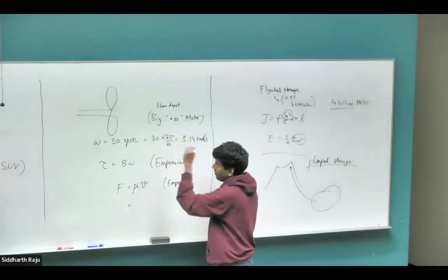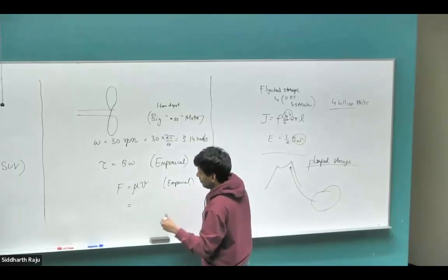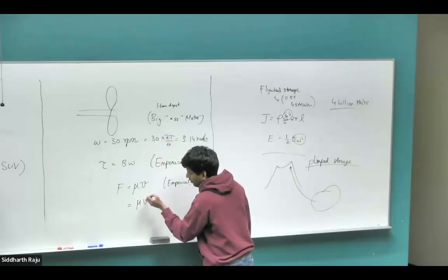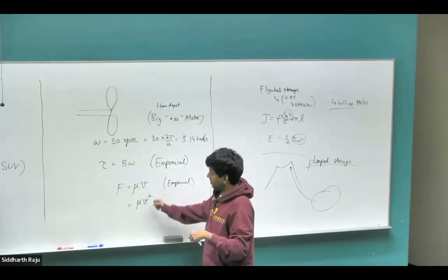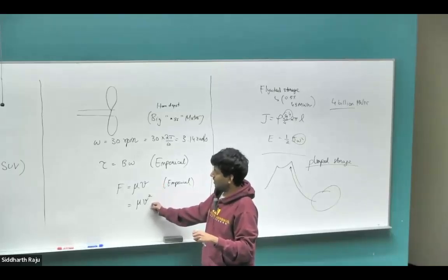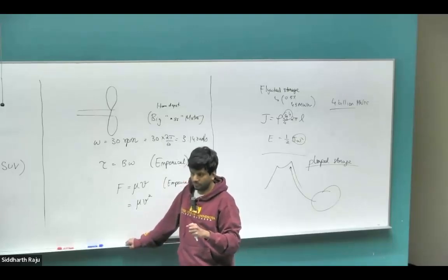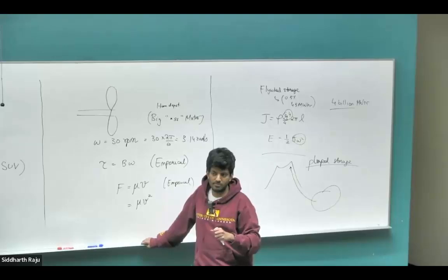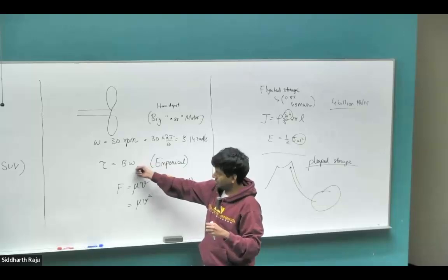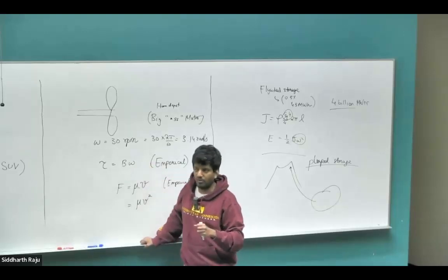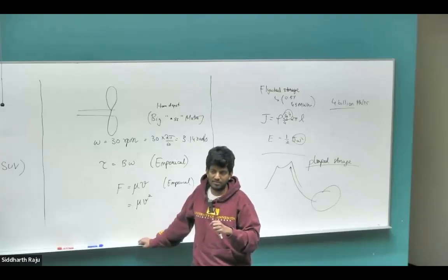Say we have the case of the fan blade that's spinning in air. In different scenarios, we would use this formula, mu times V, or sometimes we'll use mu times V square, or in the case of a ball spinning in air, sometimes we can use this, sometimes that will be more applicable, right? Anybody want to tell me when you would use which one? Even in the case of the fan, when it's spinning, sometimes you want to use B omega as the expression. At other times, you would prefer to use B omega square because that more faithfully represents what is happening in reality. If it's turbulent?